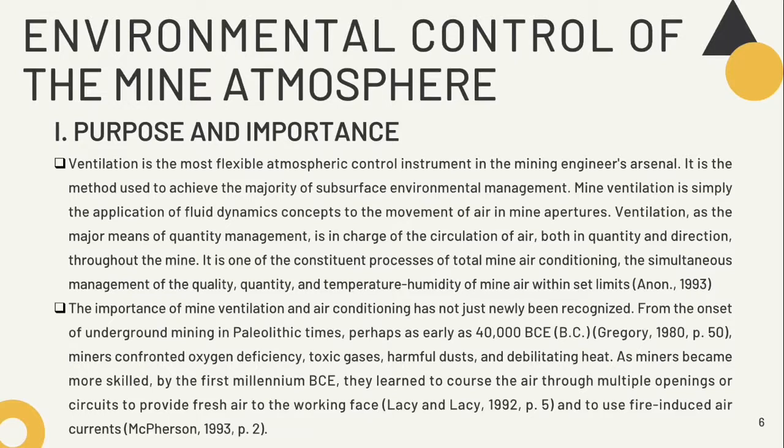Ventilation, as the major means of quantity management, is in charge of the circulation of air, both in quantity and direction, throughout the mine. It is one of the constituent processes of total mine air conditioning: the simultaneous management of quality, quantity, temperature, and humidity of mine air within set limits.